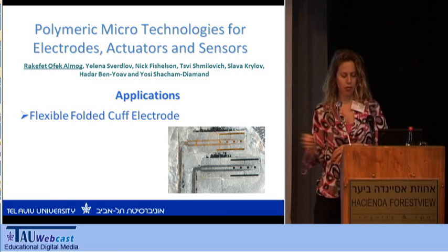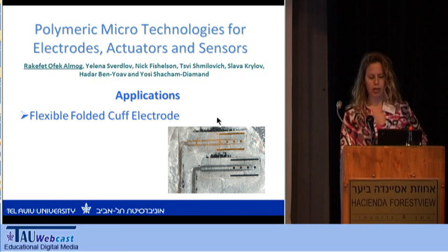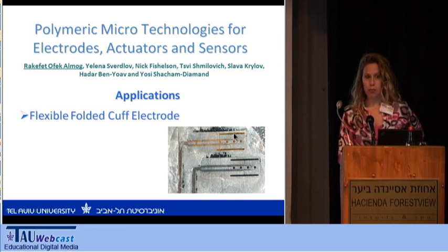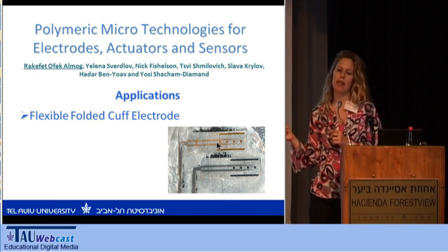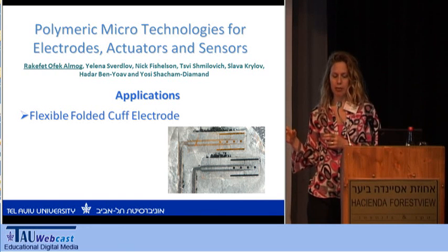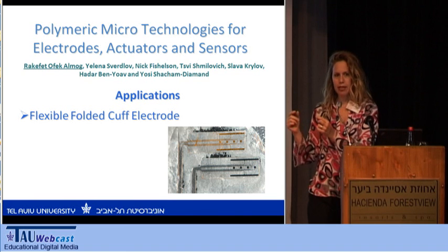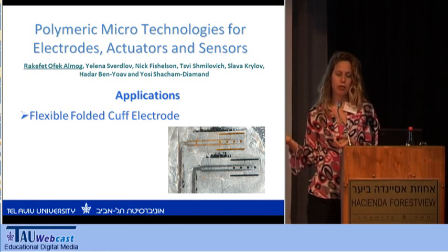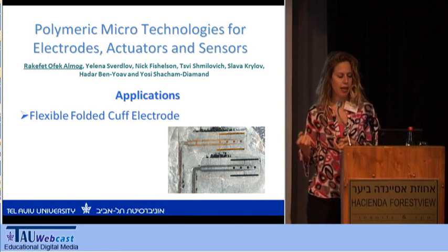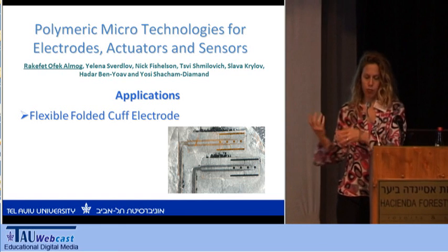to do everything. So for the electrode, we developed a photolithography process. The electrode is very thin. It's a polymer such as SU8 or polyimide, 30, 40 microns, and it's thin and can be folded. That, of course, cannot be done in silicon, and that's one way to do it.